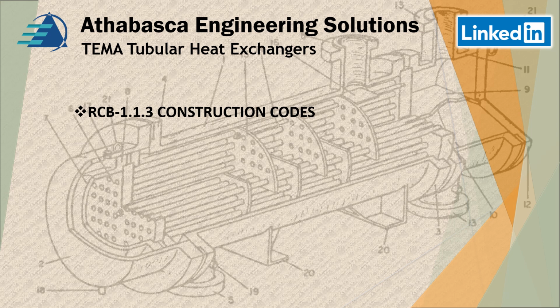It has to do with the construction codes, and this is more about definitions. Important to get this behind us. So TEMA is based upon ASME Section 8 Division 1, and throughout this document it'll be referred to as the code. It doesn't mention anything about Division 2 or Division 3. It's Division 1. So just be aware of that. And if you want to know the differences between the different code divisions, I have a video that you can look up in our library, and it talks about the differences.